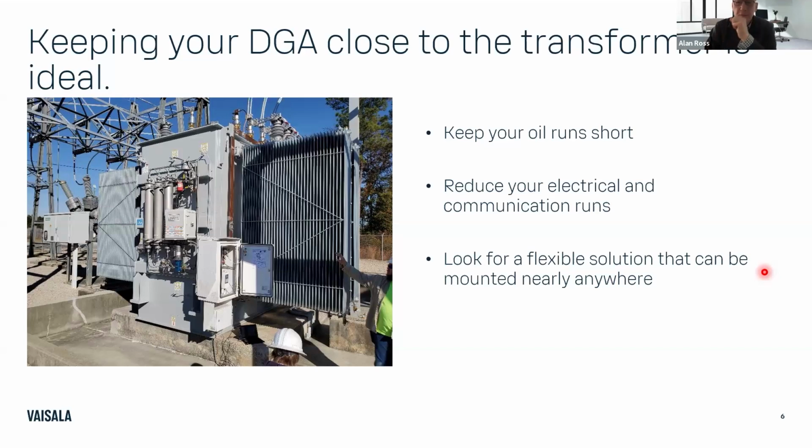I can tell you from practical experience from my years in the industry, the number of times where a monitor needed calibration, people don't do it. They don't realize it because, guess what? The person that bought the monitor and knows about it has retired. And now when you say, hey, you've got to recalibrate, is the data you're getting because it's not calibrated, or is the data you're getting real? That becomes a big issue because that's where you get the false alarm. It shows that there's a problem, you recalibrate the monitor, and guess what? You don't have a problem anymore.